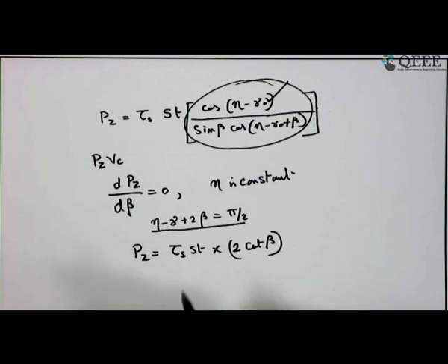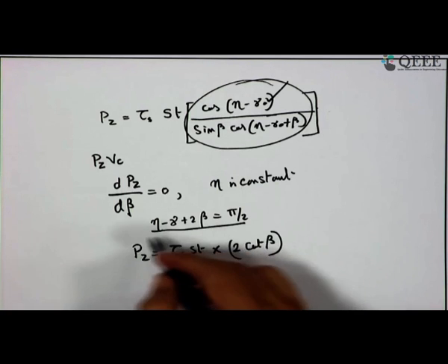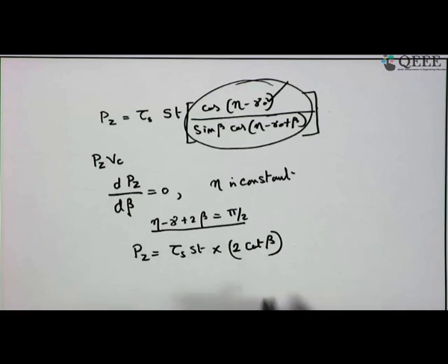Suppose you use this relation to estimate the force in machining mild steel, which is a ductile material. Your estimated value and the actual value measured with a dynamometer differ, and the dynamometer gives a higher value. So, friend, this is an underestimation of the force, and that is why we cannot use it for this purpose. This will be good for brittle material, plastic, cast iron and so on.